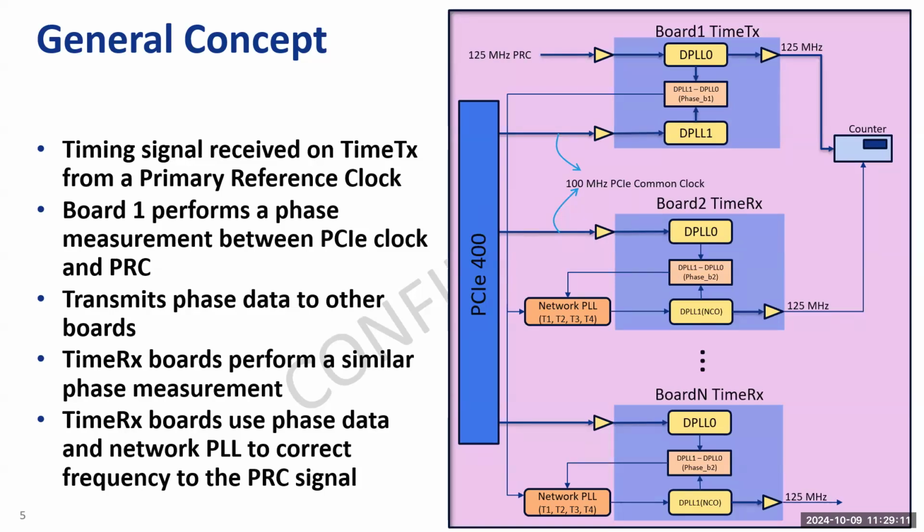So it means that you have to either add additional filtering to the measurement, and then of course if you have large offsets like you highlighted up to 300 ppm, then that also becomes an issue, because 300 ppm translated to phase is about 300 microseconds per second drift between the two clocks. So either you have to make multiple measurements very quickly to try to avoid seeing that, or you're going to have that incorporated into your error, right?